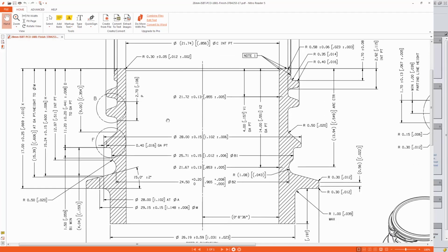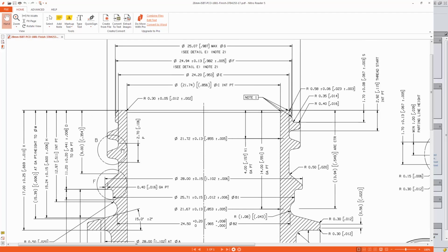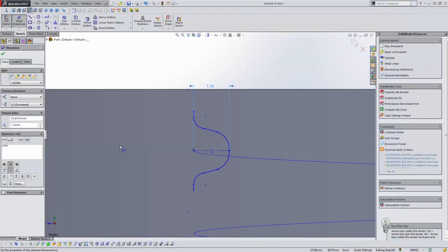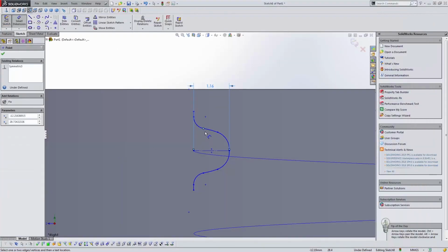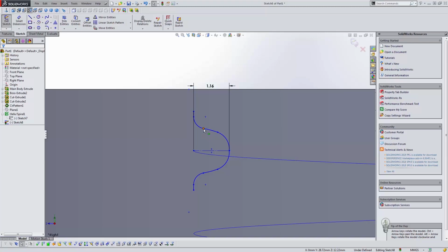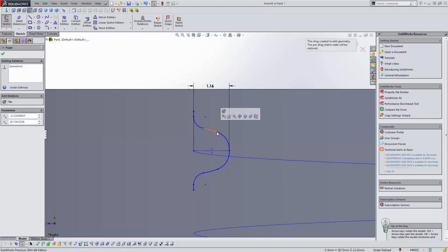And then I'm going to drop back over to here. It doesn't really give the top tooth height, so we're going to visually try to match this. So I'm just going to come in here, grab it, and get it close. Again, this isn't going to be critical in this scenario. And in the newer SolidWorks, all you have to do is click the top circle and tell it the thread you want, and it already has it in there, and you're done.